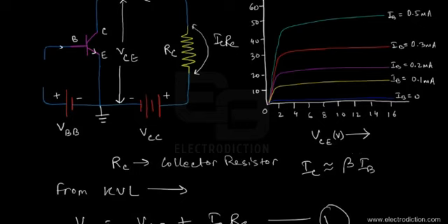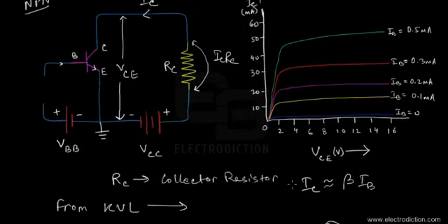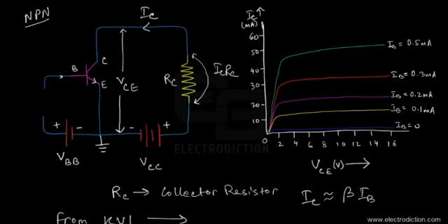So we can see that the collector current depends upon the input base current. If the input loop is open circuited, there won't be any input base current, so as a result the collector current would be 0. Under these circumstances, with no forward bias applied across the base and emitter terminals, the BJT becomes an open circuited circuit element.